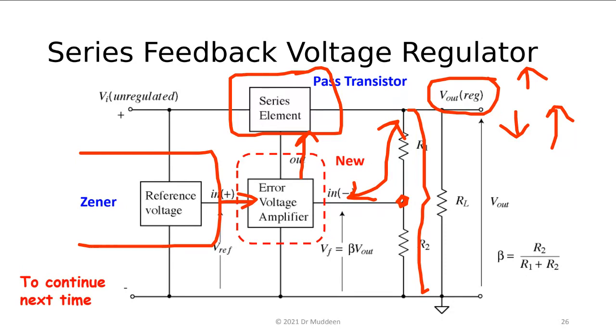Right, the reference voltage. This is our Zener reference. Remember, once you are designing a voltage regulator, you must have some reference voltage around to work with. The only way you can know if a voltage regulator is supplying some design voltage value is if you have a reference. It has to have a standard to go by.